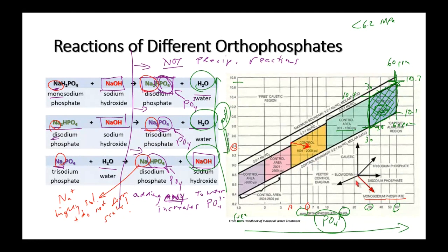Monosodium phosphate has the effect of, and I'm going to resolve this into vectors now, increasing the phosphate, because like I said, every single one of these affects phosphate. Every single one will increase the phosphate. And I also want to reduce the pH. Well, how the heck is this stuff going to reduce the pH? It reduces the pH by consuming sodium hydroxide. As you can see, that's what monosodium phosphate does. Ain't that neat?